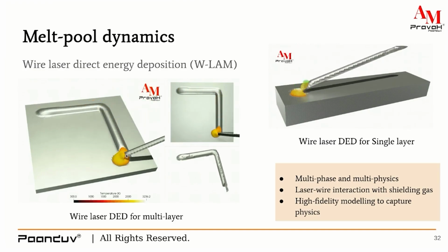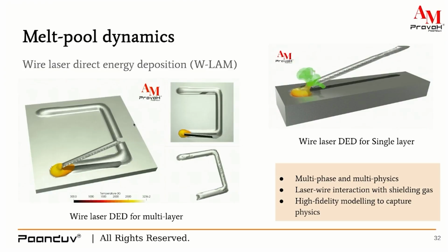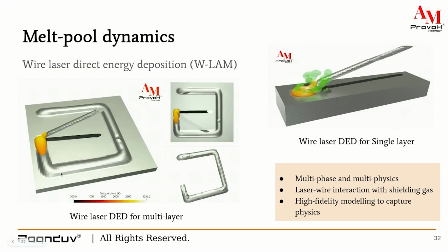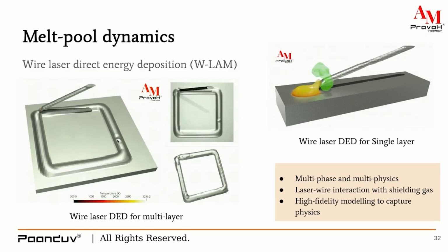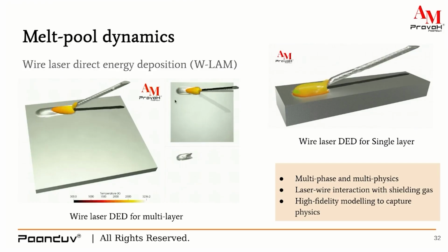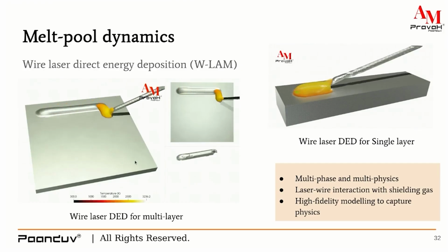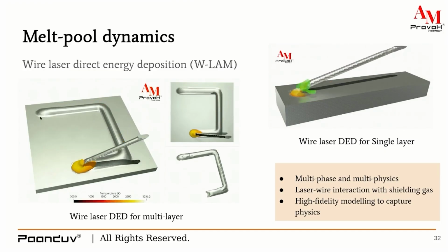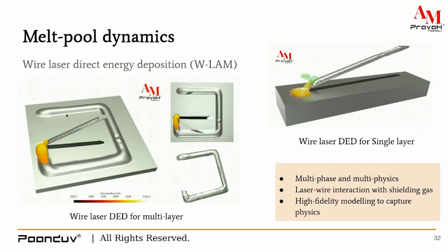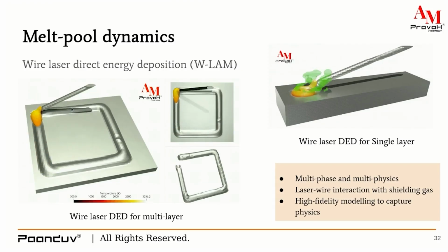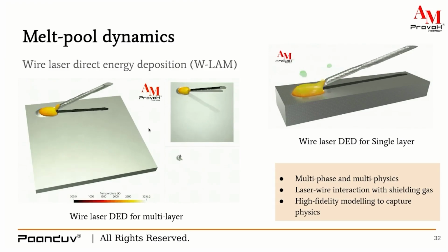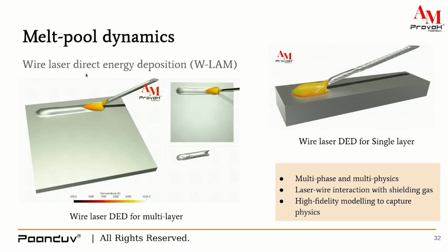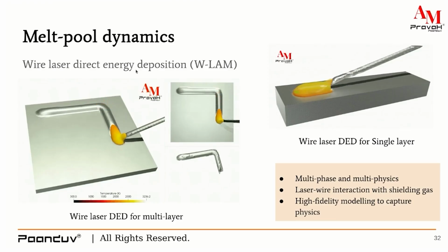This is a 3D representation of the grain evolution in this process. Now, apart from the 3D information, what you can do is you can cut down these sections at different times and different locations, from which you can have voxel size information and grain evolution information, in which manner the grains are being evolved. You can correspondingly have the information about crystallographic information, in which particular direction the grains are being evolved.